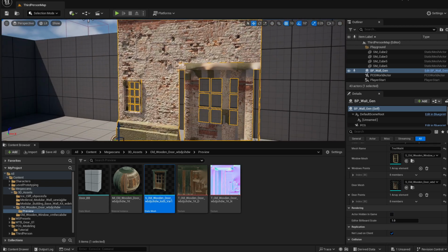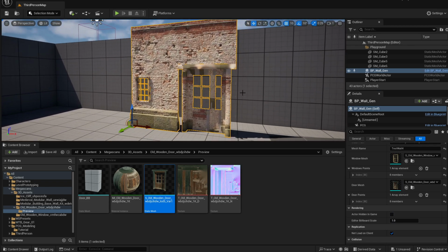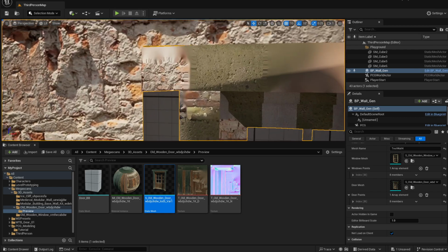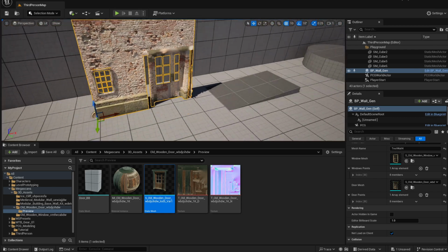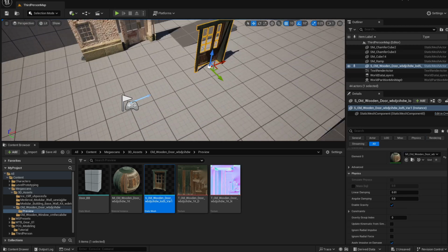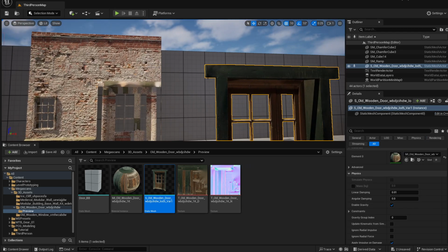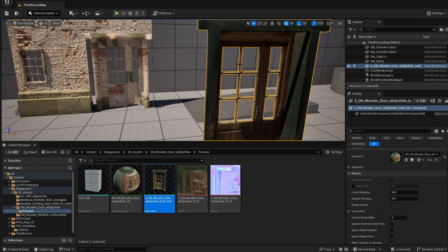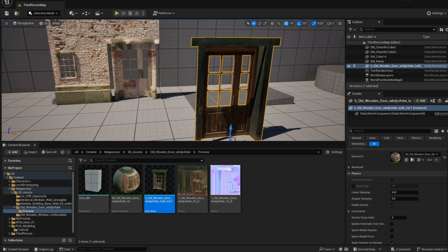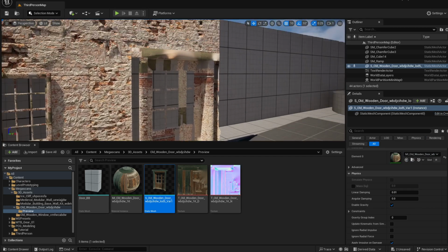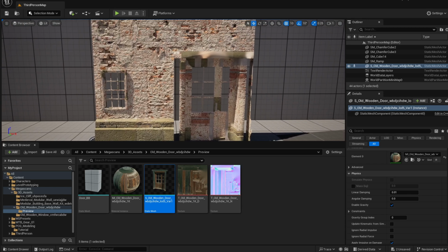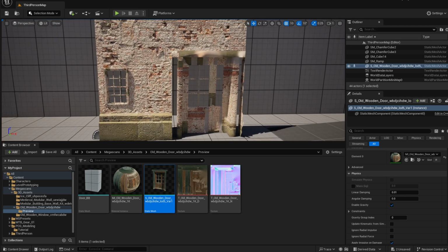Okay, so here is where this size property that we created can be used, because our model for the door, let's put it here with the proper material, has this sticking out parts at the end. So the bounding box is actually bigger than the hole that we want to cut inside the wall.